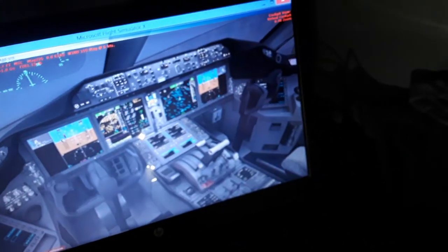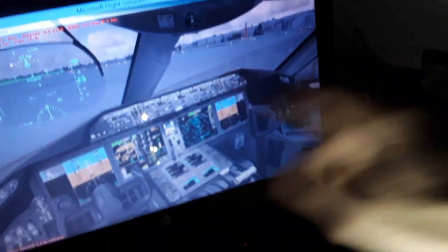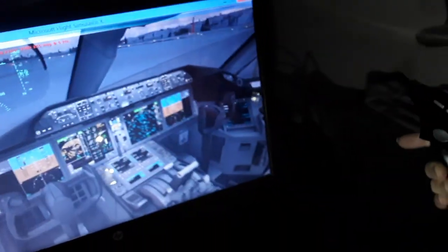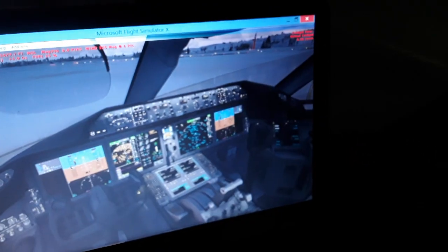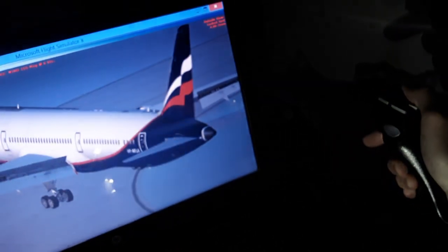You move the weight of the aircraft up and you move the weight of the aircraft down to descend, the pitch axis of the aircraft. The side stick in the Airbus, back and forth. The yoke, the whole yoke, back and forth in the Boeing. Also you can see both sides in the Boeing move together, and the control wheel. So you use the elevator for climb and descent.